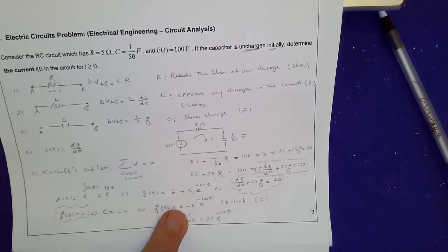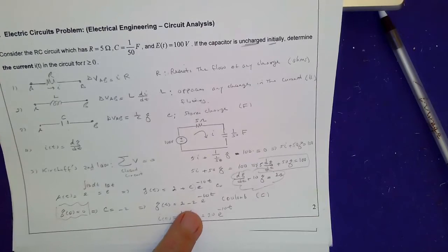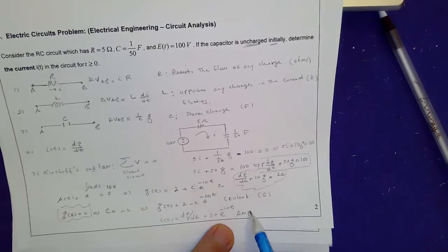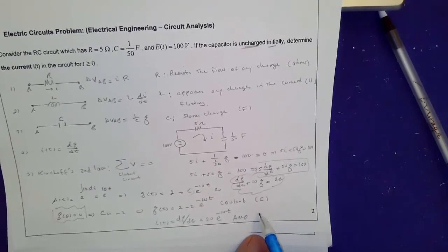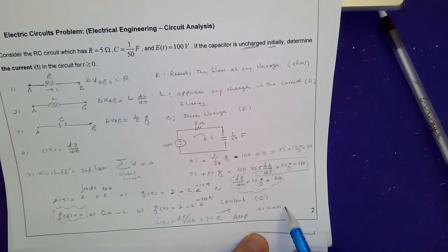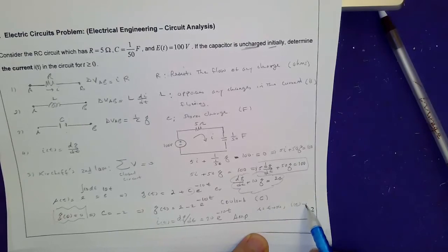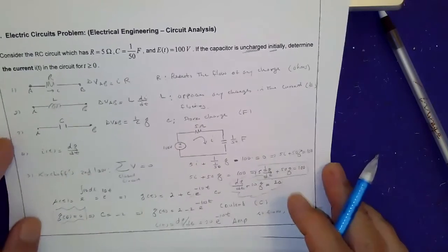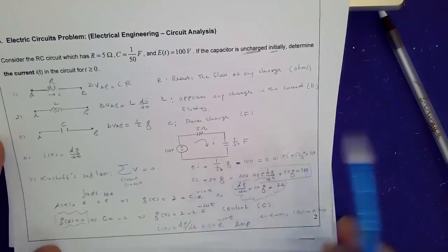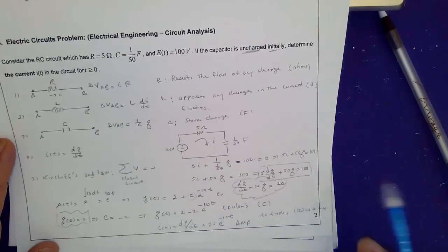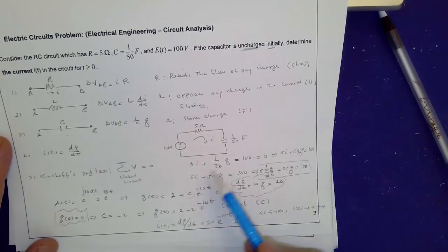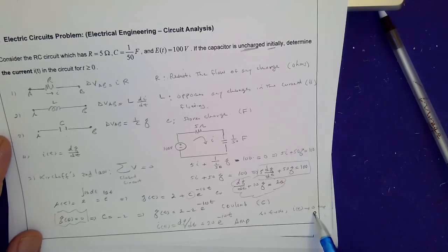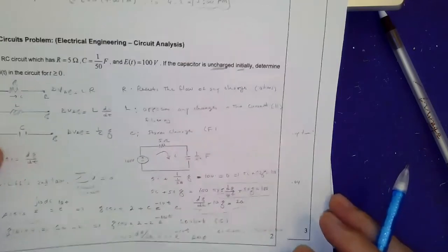the constant goes to 0 when you take the derivative. The other term would be negative 2 times negative 10, which is 20e to the negative 10t. And this would be so many amperes. And once again, notice, as t approaches infinity, guess what? I, the amount of current, gets close to 0 amps. In other words, the longer this stays there, in a long period of time, eventually the current drains out and it gets close to having 0 ampere of current.